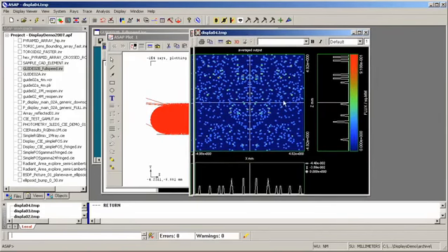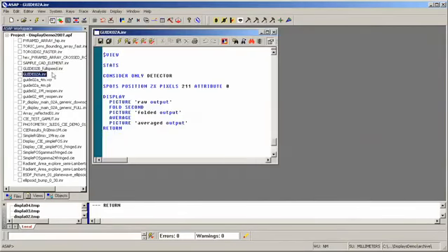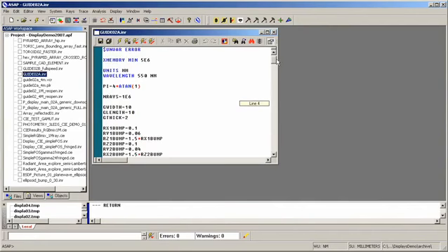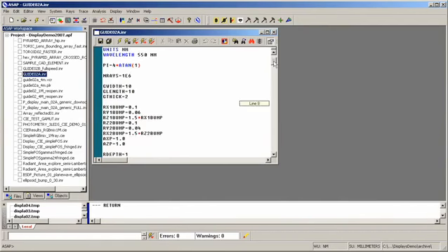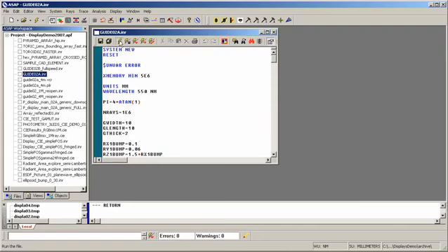I've averaged the results here, and one thing you'll notice is that this is a terribly grainy output out of the top of the light guide. This wouldn't be obviously usable, but remember, we started out with only 11,000 rays, so we're not really sampling the top surface very well. Let's now take a look at the same problem, but with more rays. So in this case, I've set 1,000,000 rays. I'm going to skip a significant number of the rays, so I will plot only 1 in about 10,000 rays, although I will trace all of them.